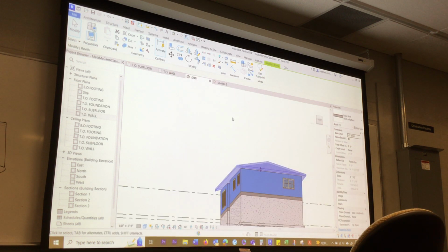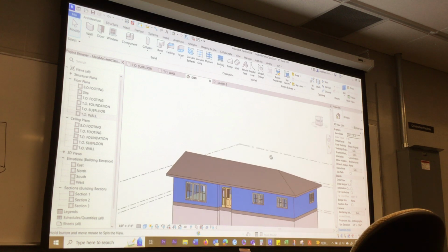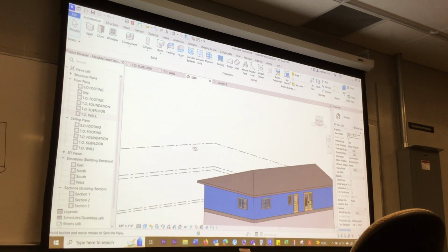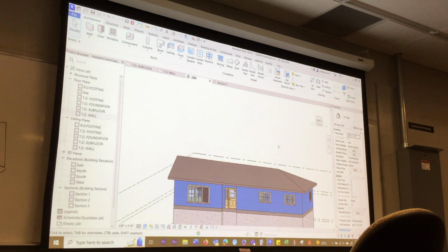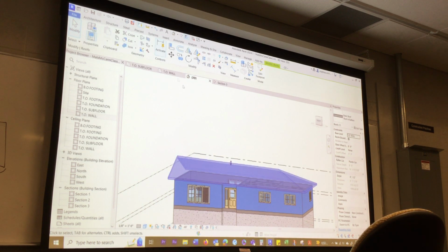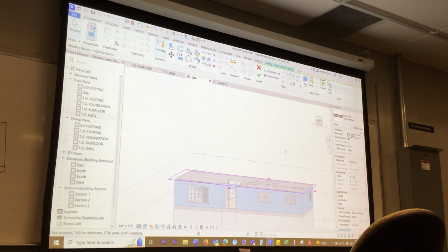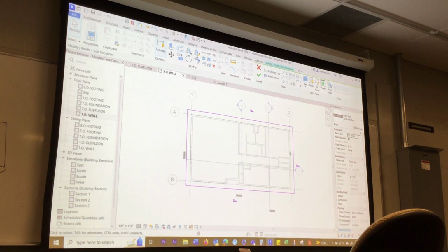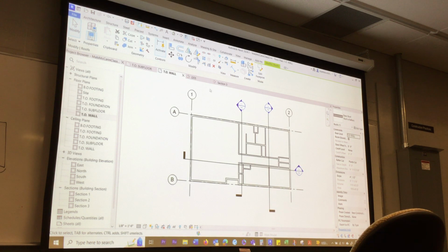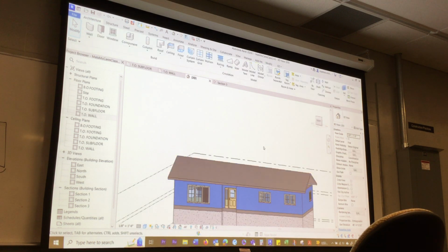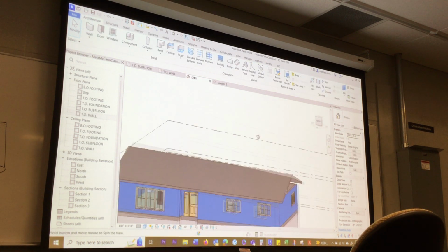Now I got a hybrid. Now I gotta go fix it, because I don't want it like that. Click on the line, uncheck define slope. There's some other stuff you can do in there too, and then check to finish. When you're in sketch mode, you always have to either throw it away or check to finish. Alright, so how do we make this thing look normal?